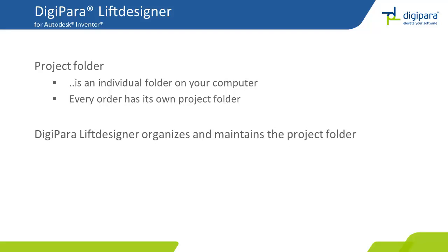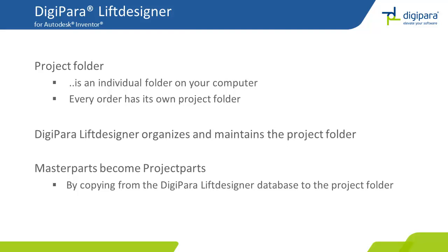DigiPara Liftdesigner organizes and maintains the project folder, and that means that we also clean up this folder if some file is remaining from an earlier modification. And it's important to understand master parts become project parts. By copying from the Liftdesigner database into the project folder, the master part becomes a project part.